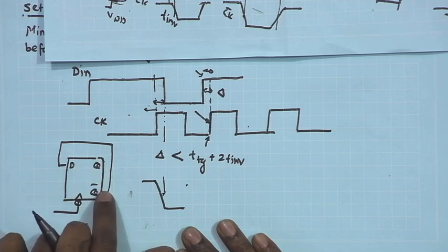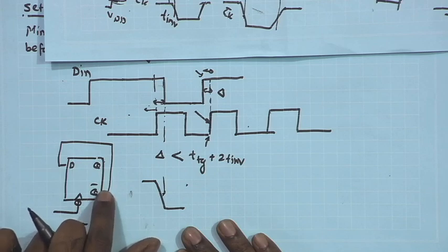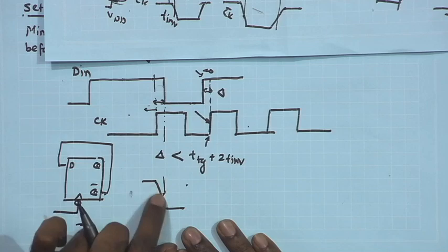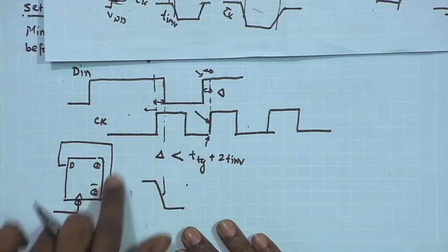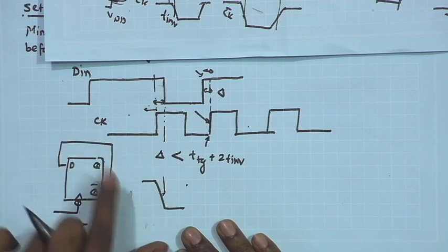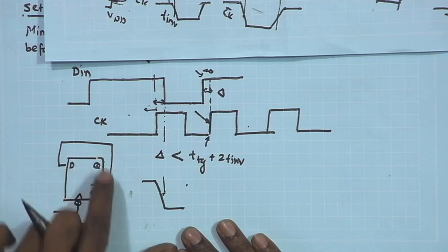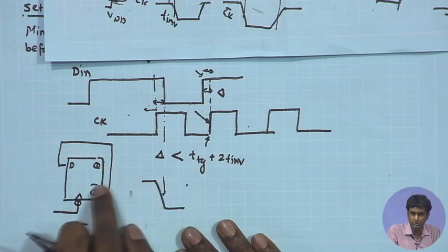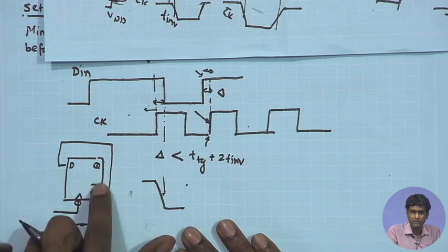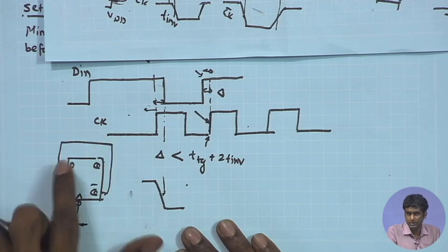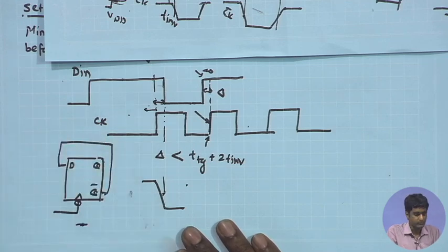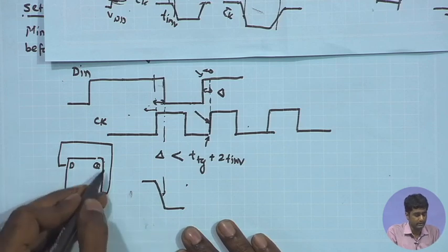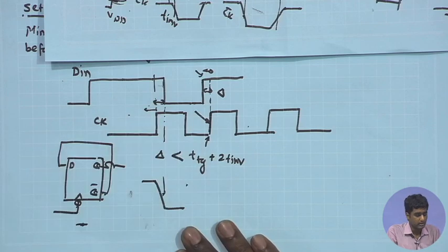I do not need to worry about a sudden change in Q bar just before the downgoing edge of the flip flop in our case, because Q bar is connected to D. So, D is automatically only the inversion of the Q, which was stable all throughout the last period. Therefore, the setup time will not be an important concern in our case. However, clock to Q delay will be a concern because we are concerned with the total delay of the ripple propagation from the input to output.